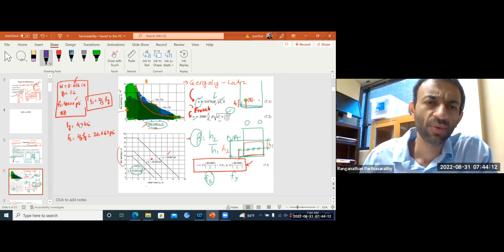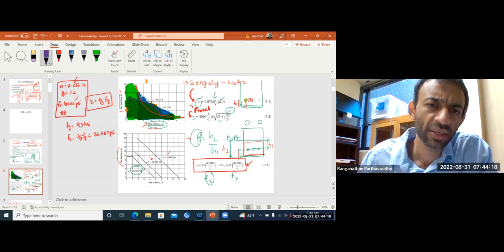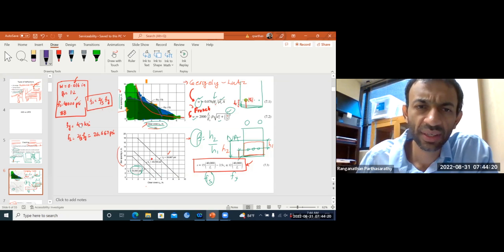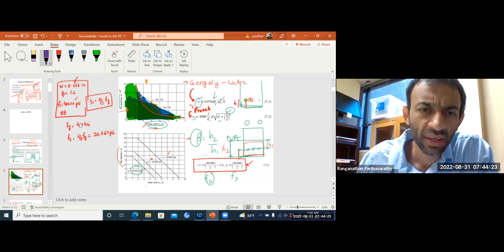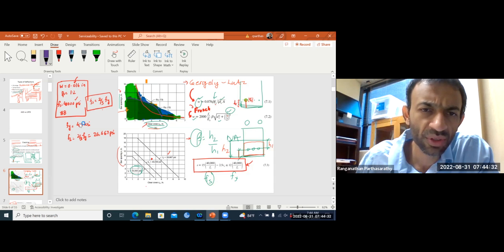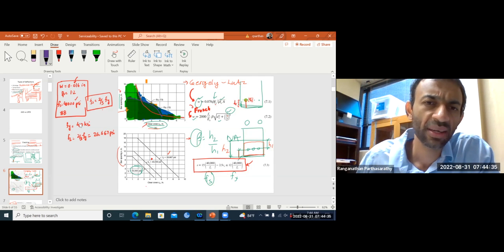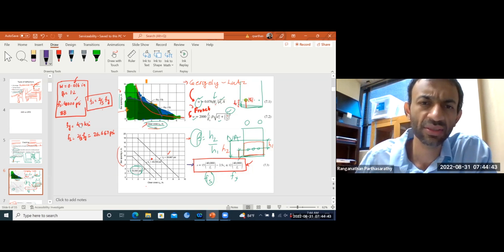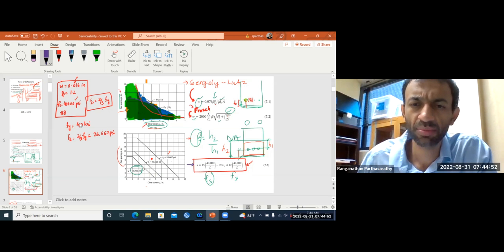Basically, what they are saying is if you have a certain clear cover, let's look at, for example, the Frosch equation, the purple curve. If I have a clear cover of 2 inches, suppose, then I cannot have a bar spacing of more than 8 inches. If I have that, my crack widths will become unacceptable. That's how you read these two curves. Now, what is followed in your code specification is a compromise between Gergely-Lutz and Frosch. That's the straight line that's much easier to implement.